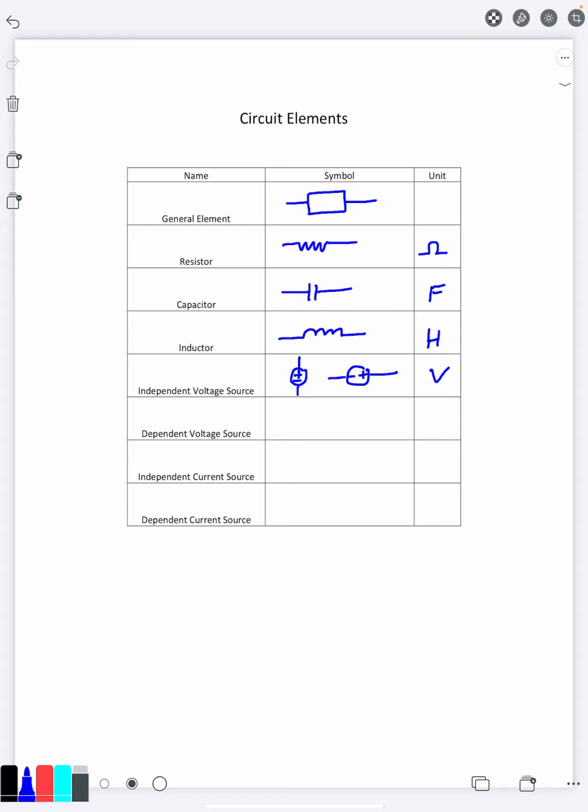Now, what does that even mean here? So if I write a voltage source and say it's 5 volts here, what that means is that if you were to take a point on top of the voltage source, the plus side, and look at the comparison point on the negative side of the voltage source, there is guaranteed to be a 5-volt potential between these 2 points.